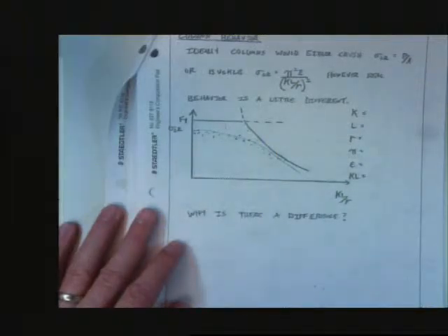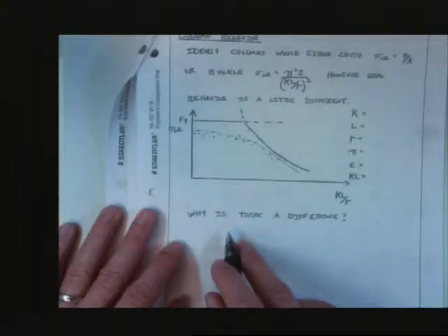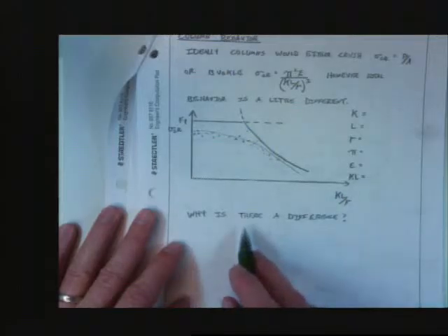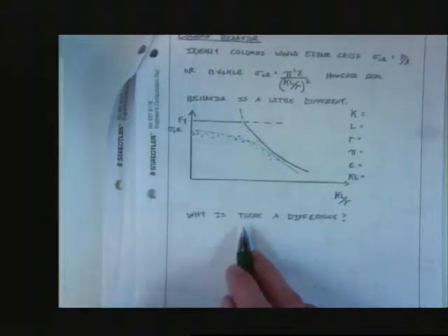Imperfections, residual stresses, uneven loading, which in effect are all imperfections, aren't they? It's all imperfections, but residual stresses and imperfections are two different beasts. There's imperfections over the length, out of plumbness, out of not being straight. Then there's uneven loading, and then there's our favorite, residual stresses that come from the rolling process.